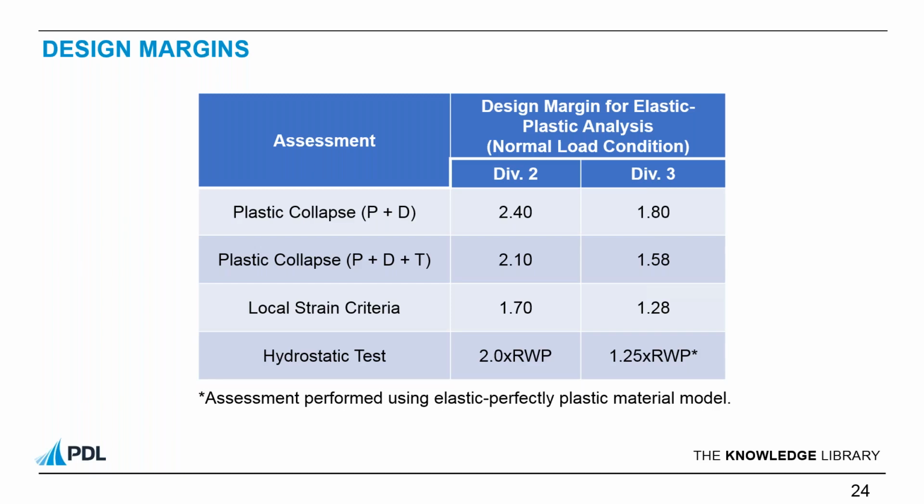The other one that came in just before was, when we're talking about fatigue, how do we actually know if the product is likely to be fatigue sensitive? Okay, so, as I briefly mentioned in the slide, section 5.5.2 of ASME VIII Division 2 essentially gives you a procedure for determining whether or not your component's likely to be fatigue sensitive.